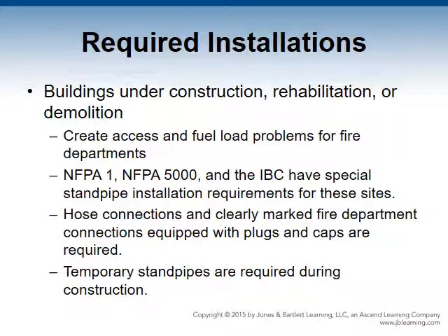Buildings under construction, rehabilitation, or demolition. Construction and demolition sites create access and fuel load problems for fire departments. The presence of construction material complicates these jobs. NFPA 1, NFPA 5000, and the IBC all have specific requirements for standpipe installation and FDCs for these sites. Under certain circumstances, a temporary standpipe may be required.